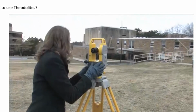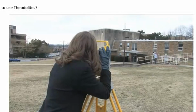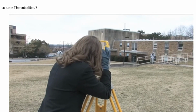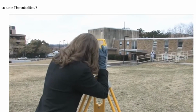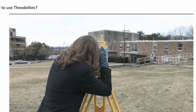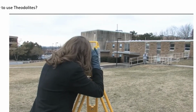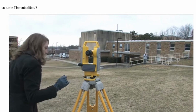Once the rod person has returned to point A, the instrument person may proceed to fine-tune the instrument back on the HI. Notice that the instrument controls are now facing away from you. Now proceed to rotate the horizontal and vertical angle locks, and then proceed to read the upper and lower stadia readings, as well as the vertical angle off the instrument, and record in the field book as a secondary measurement at point A. The objective now is to turn the angle to the right a second time.